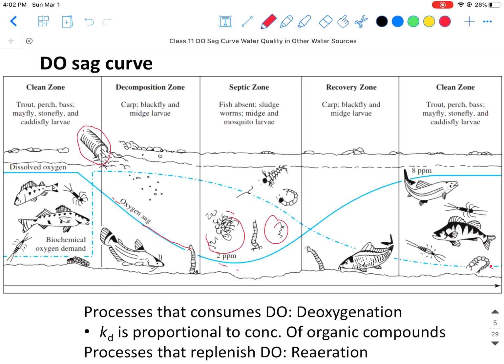This is mainly because in the atmosphere, there are a lot of oxygen molecules, right? So these oxygen molecules are being actively dissolved into the water. And let's say if there is more turbulent flow taking place, right, and the flow is also very active, then it's even easier for the oxygen to dissolve into the water. So there's always some oxygen being supplied into the river.